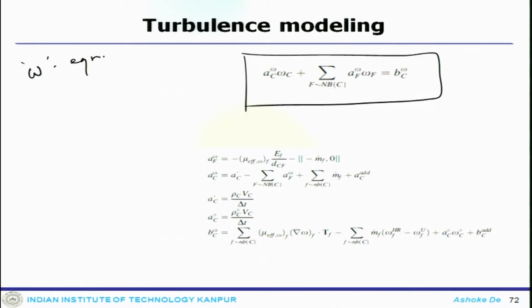Now, one important thing that happens is the calculation of the wall function, because all these turbulent equations are used, and near the wall, flow field resolution is very important if you have a domination of the viscosity. To resolve that, typically there are 3 different layers into which the flow can be divided. One is called the viscous sublayer,